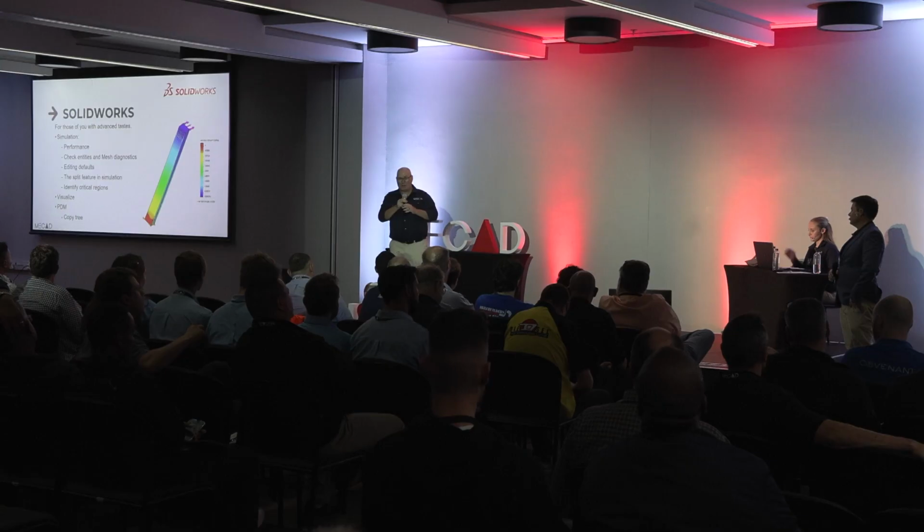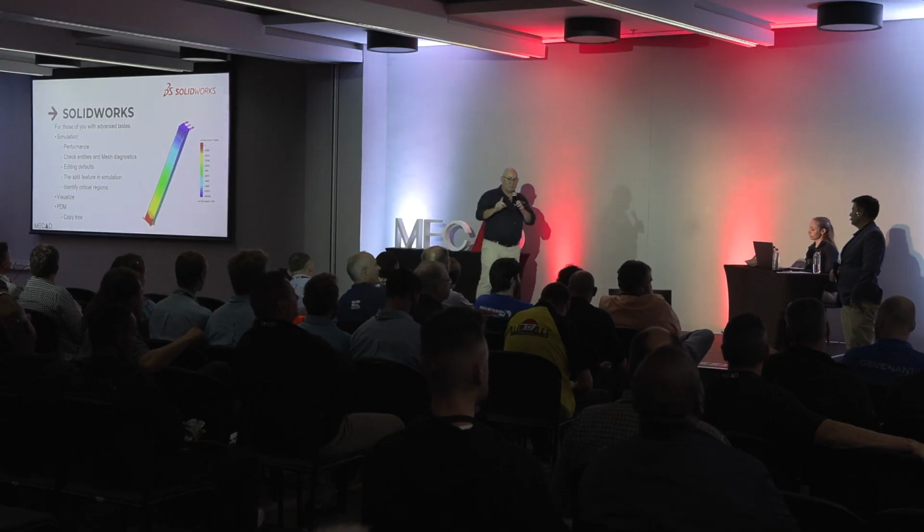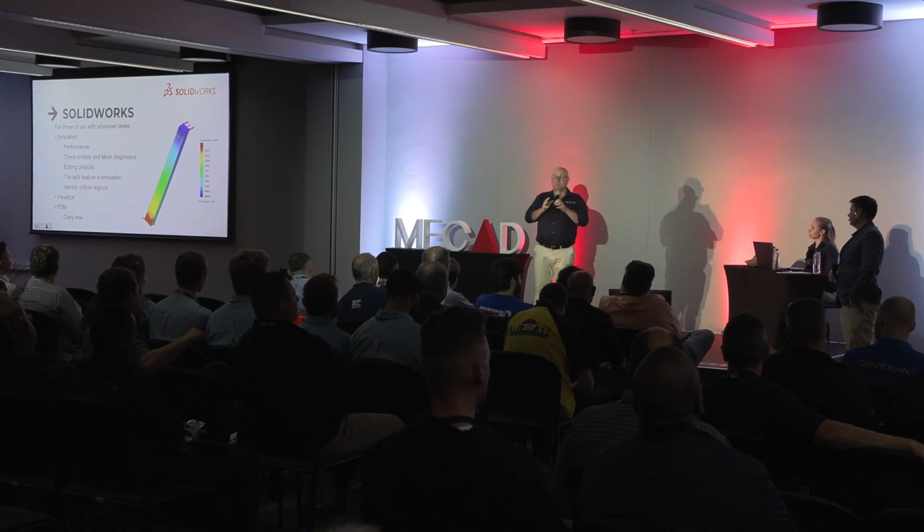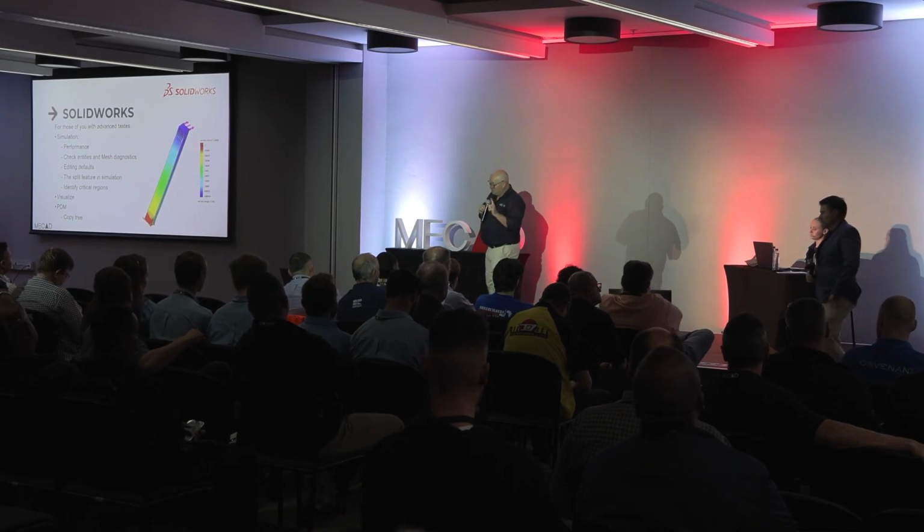Is it a resource problem or a simple one? He's asking about using references, designing parts in context, references, and moving things. There's no problem with the software to handle it. It's our ability to manage all those files. We can mess that up very quickly. It's a very good design tool, but I would say break the reference and redefine that file in its own right, because then you can move that and they're not connected anymore. If you think it's doing something that it's not supposed to do, mail support, and then we can analyze the file. You can take it away, Angelique.